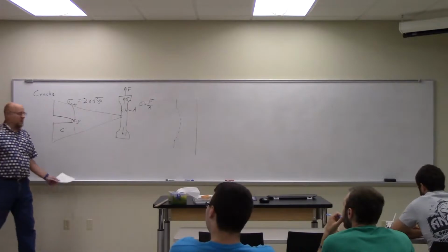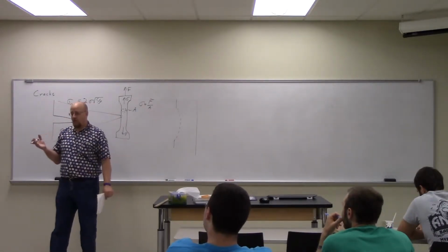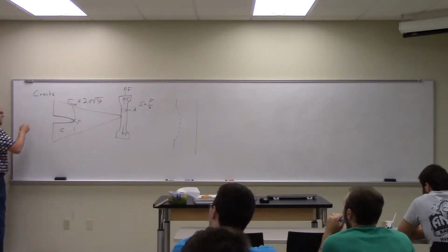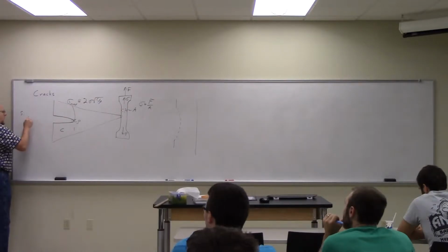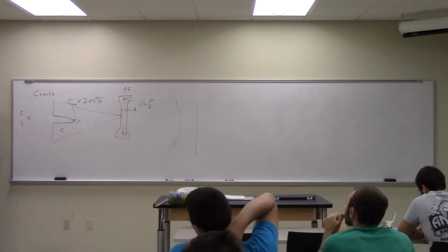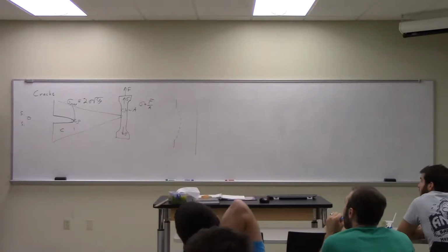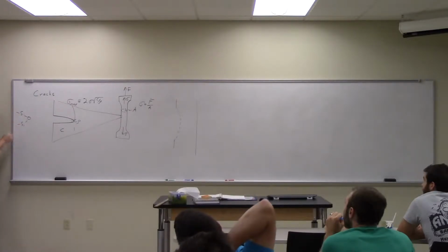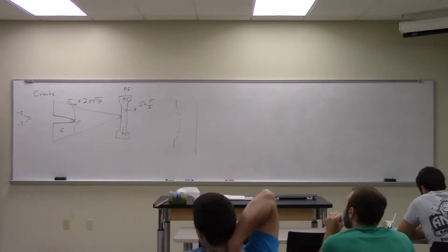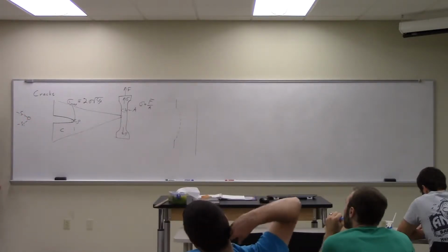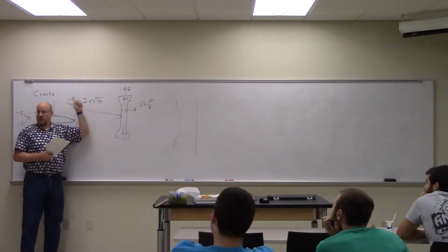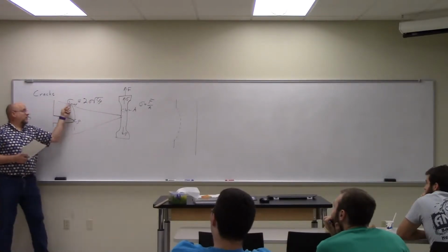Right. So even if it is what's called an atomically sharp crack, meaning I can get down to the atom, I've got a silicon, an oxygen, and a silicon at the tip of that crack, where the bonds that would have been to an oxygen over here have been broken. That would still have a radius, which is essentially the silicon-oxygen bond dimension. And that's a really small number, which means if I have an atomically sharp crack, the stress at that crack is enormous.